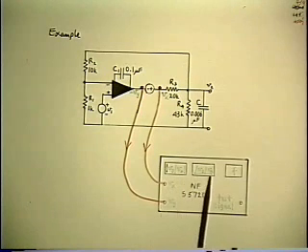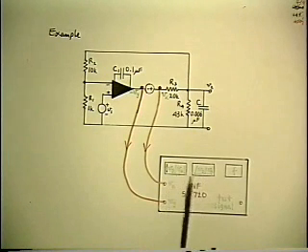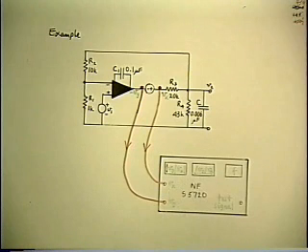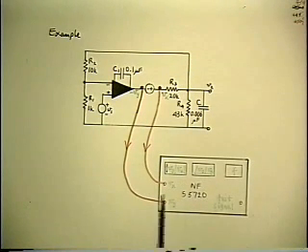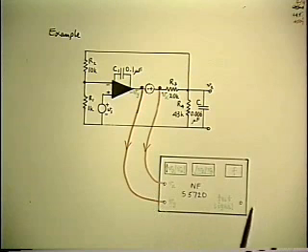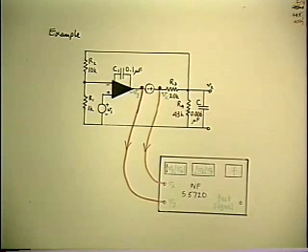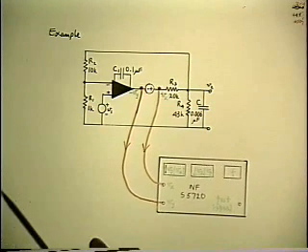But nevertheless, they do everything you want, and they give you digital readout of both the magnitude and the phase. And some of them are also computer controllable, so you can quickly go through a whole frequency run and get the answer in no time at all. So whatever instrumentation you want to use, you've got lots of choices, and you can trade off how much you want to spend on it. So that takes care of the measurement technique.